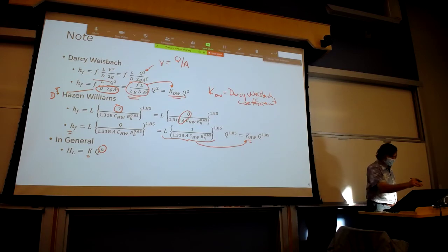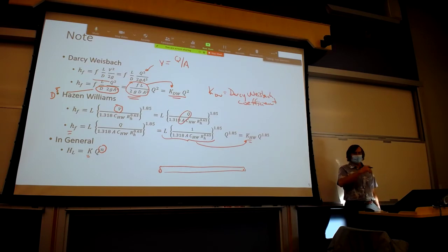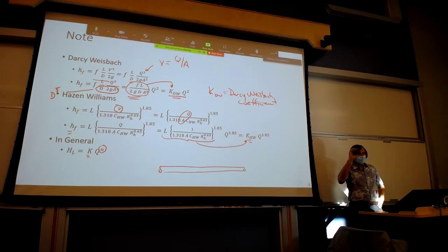For the practical application, though, in the field, what we may have is a pipe underground. And we may not know how many valves are in it, if there are any valves. Also, that pipe could have been put in the 1800s. So we don't know if there are big holes and leaks in it. We don't know the status of the corrosion until we dig it up. But we don't want to dig it up. We just want to understand the friction loss characteristics of the pipe.